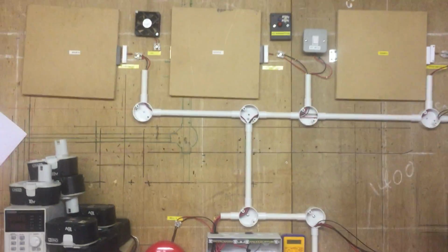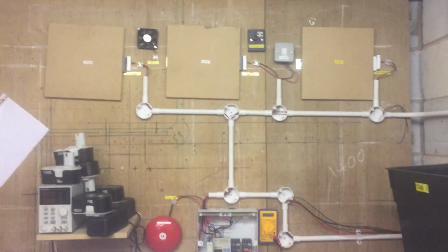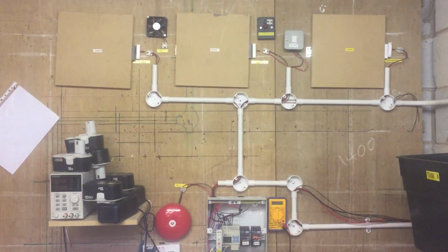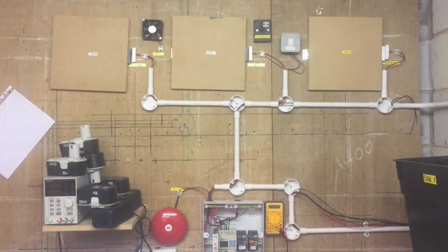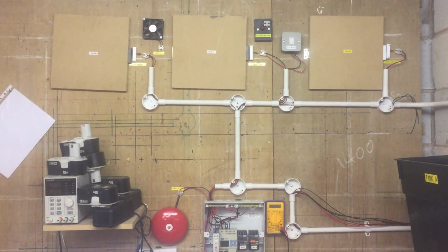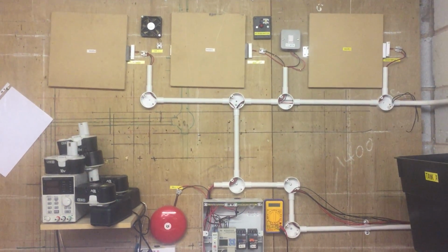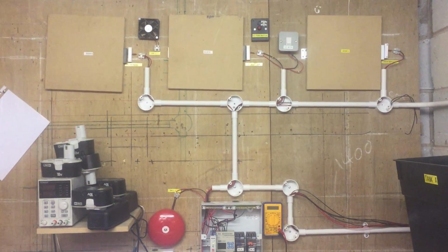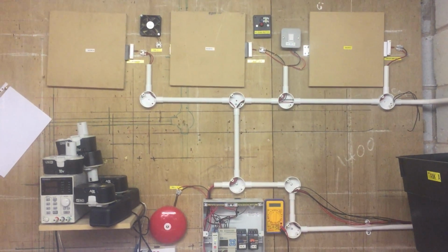We're going to give you two examples on the software today. In the first example, the timer is going to be set to 5 seconds and the bell will activate after door B into input 2 has been open for 5 seconds. In the first instance the timer will be reset once the door is closed, back to 0 seconds. So once it's reopened and 5 seconds elapse again, the bell will sound again.